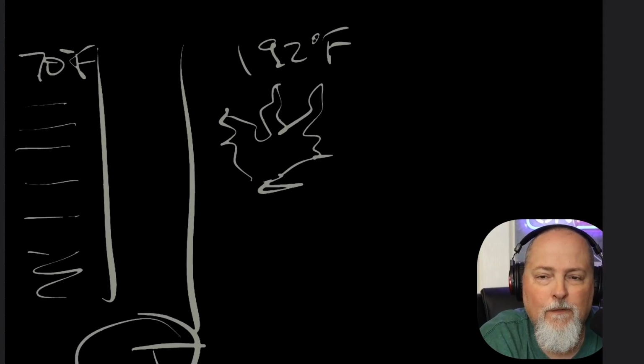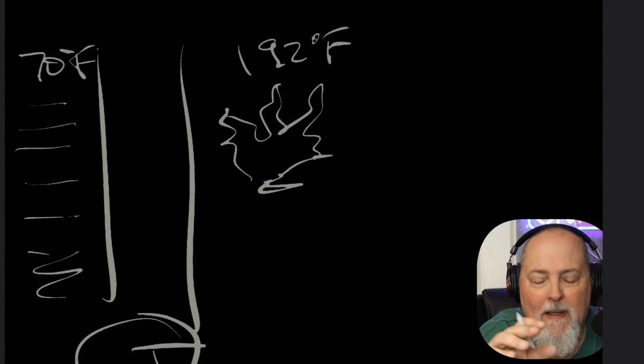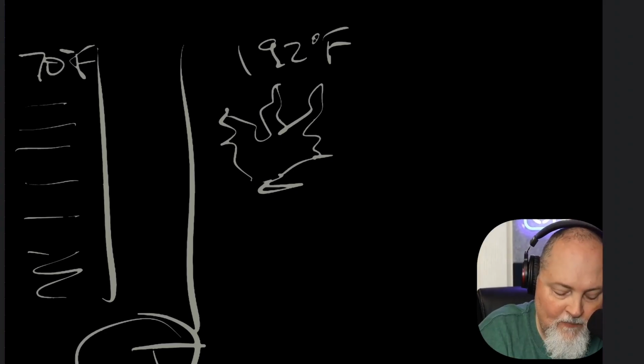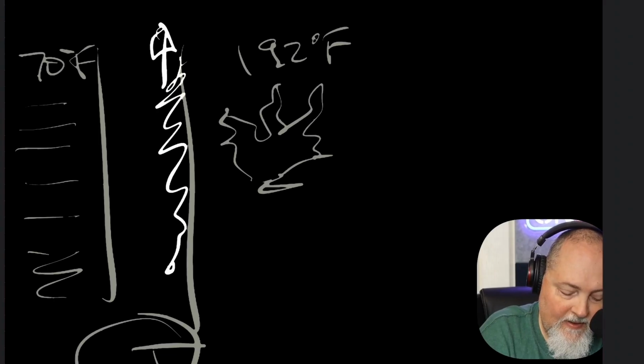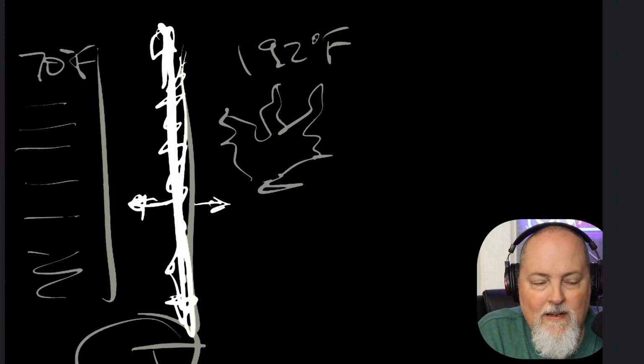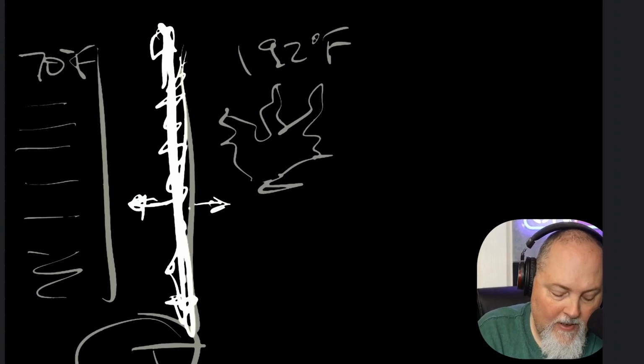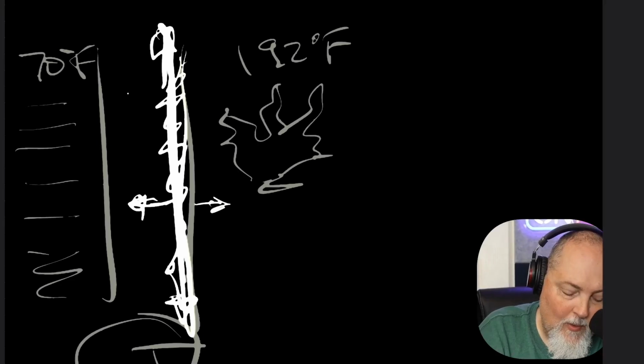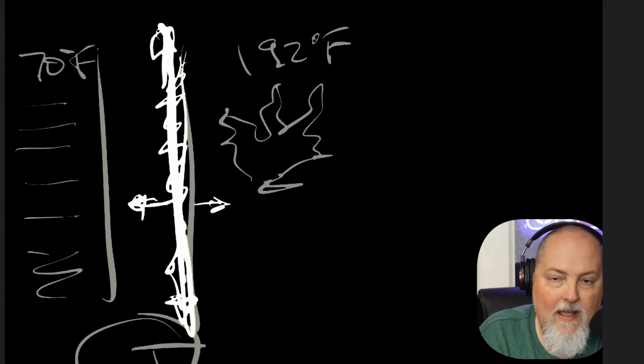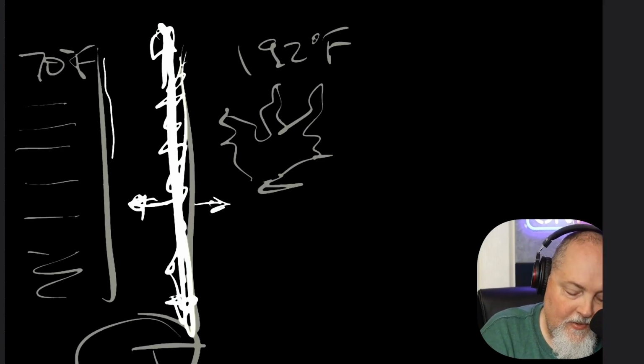If the material is fully restrained, so that expansion or contraction is resisted, then as I heat this up, this material here is expanding. It's expanding outward, laterally. It is expanding a little bit this way, but not much. Most of the time, materials will expand in their longest plane, and so it's expanding this way. If the cup has a really high modulus of elasticity, really high stiffness, then it is resisting that expansion.